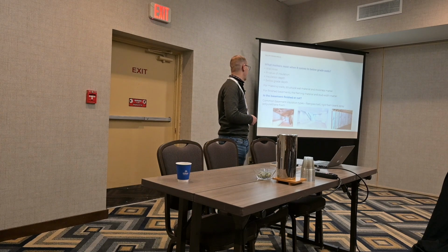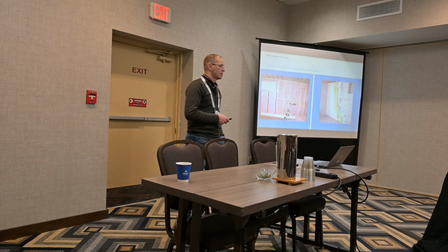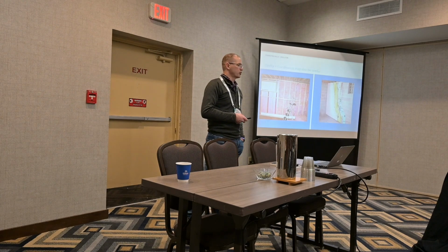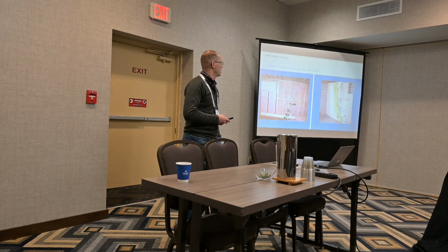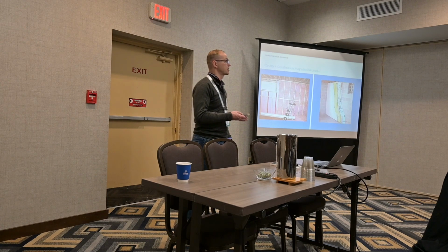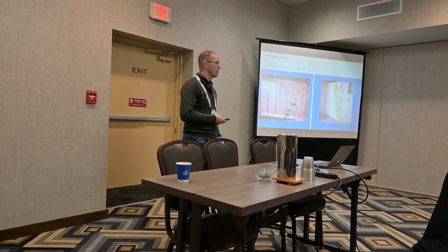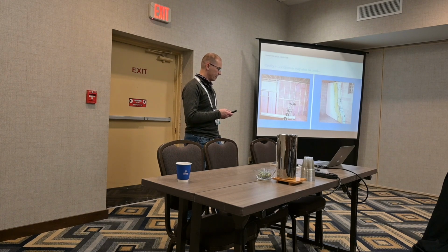Common basement insulation types, and that will also range, as we discussed earlier, with the above grade wall insulation. Okay. Cavity and continuous insulation. Unless you're there for new construction or a heavy retrofit and renovation and you were able to see this, some of it may be tough to tell if it has continuous insulation, but it does exist. Continuous insulation, interior to brick wall, has been used before and could be a possibility. So this is why it's crucial to really get the construction details on a building.